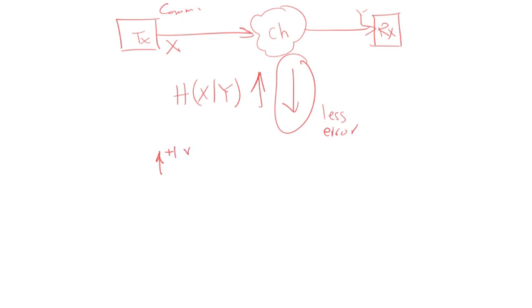Positive 1 voltage, okay? And a 0, so this is a logical 1, and a logical 0 from the transmitter is represented by a negative 1 volt, okay? This goes through the channel, which means this goes through a cable or a wireless, and then it is read at the receiver. But when I read it at the receiver, what I get actually is positive 1 in the case of 1 being transmitted, or negative 1, and then added to it some value that comes from the noise of the electronics at the receiver.